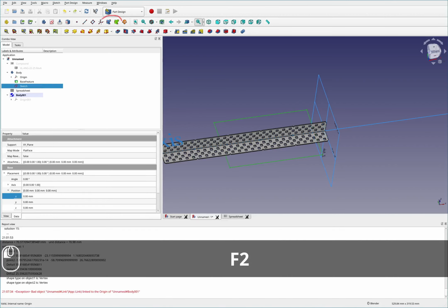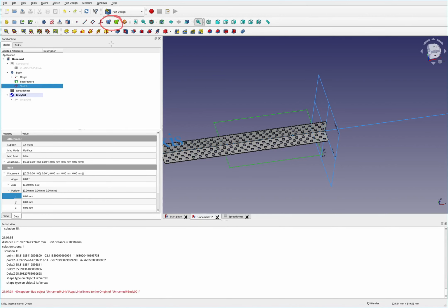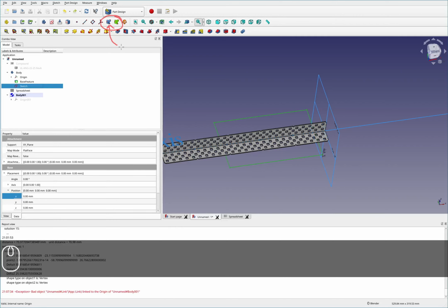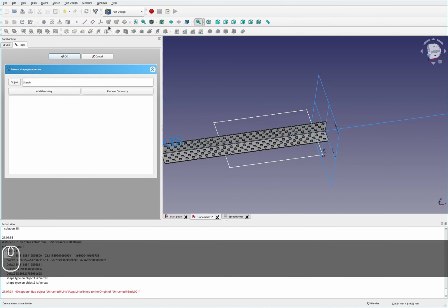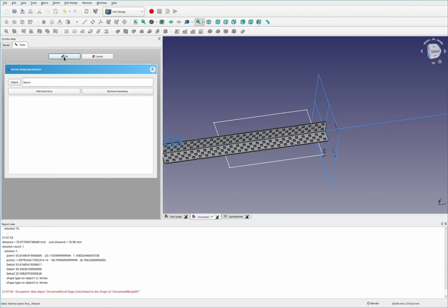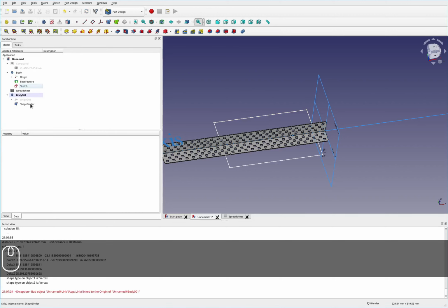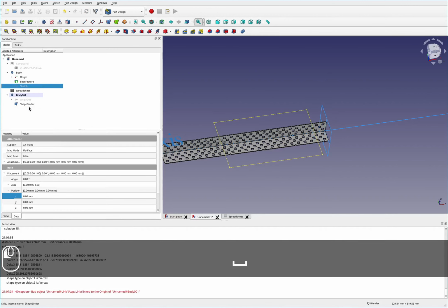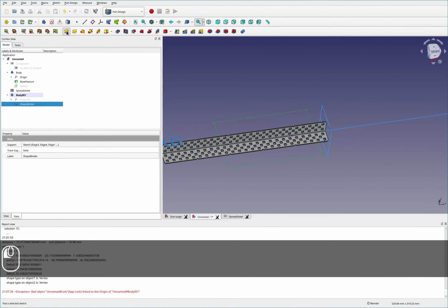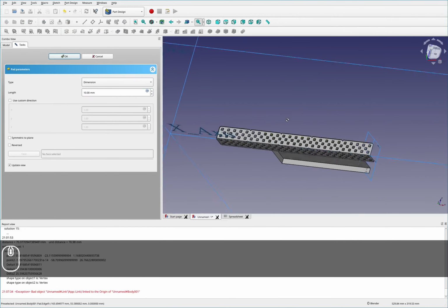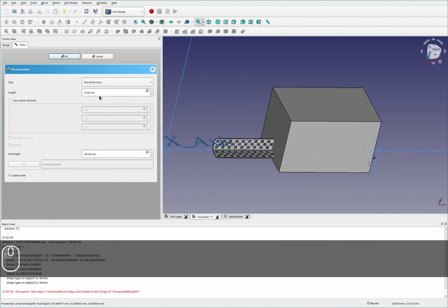So we can shape binder this probably. Here, once again, I talked about this in the last video, blue shape binder or green shape binder. For this instance, I'm going to be using the blue shape binder because it's more restrictive, but it should not matter for this. So sketch, and I guess we can add geometry. I'm not sure it wants me to select edges. Gotta go through and individually select edges, I guess. Okay, now we've got this shape binder. We can hide that. And can we extrude the shape binder? We can, in fact.